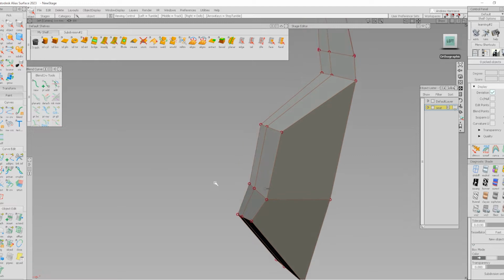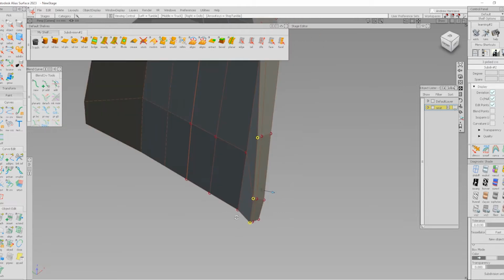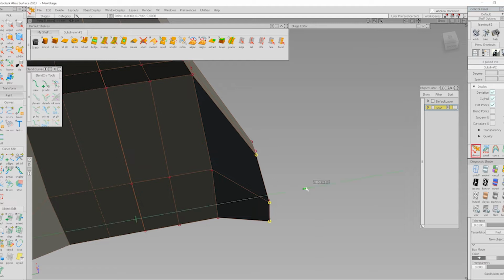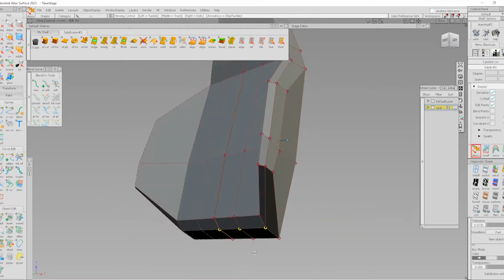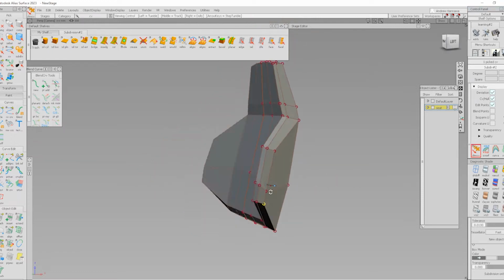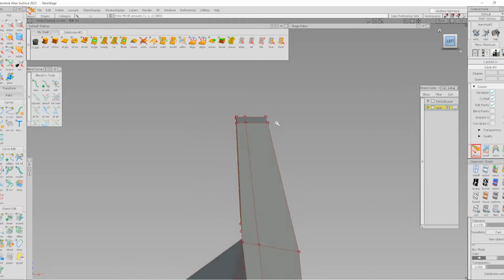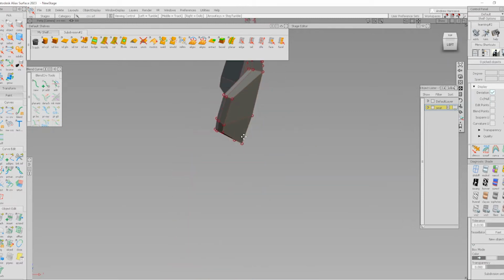Yeah, I think these ones could go a little bit forward, and then I can grab this and then holding shift middle mouse click to drag select, and then I can move them inboard. I can do the same thing, shift middle mouse click, and then move these down, get a little bit more crown on there. This one could move back. And then let's do the same thing here. Select these, move them. Let's get some thickness. All right, that's looking good.